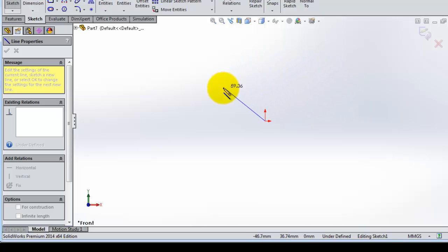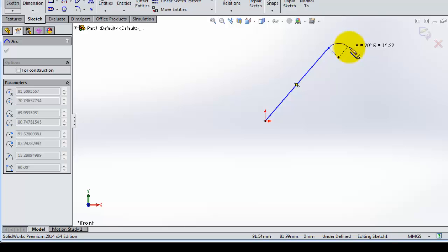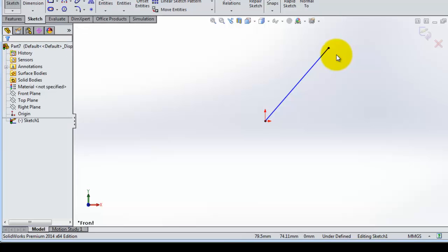That is a helpful tool, so you know the approximate length instead of making small lines or bigger lines and then redimensioning them, which might mess up your sketch. So you can pick it to be, for example, 100 millimeters, and when you click, you're selecting your point, and you are still able to use the line tool. When you are done, you can click escape or right click and select end to end your line tool.